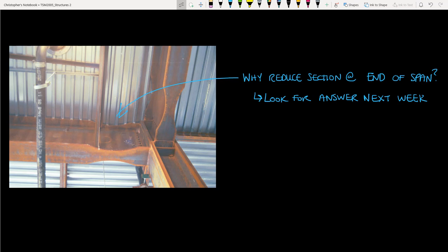This area acts like a fuse, if you've ever taken an electrical course or looked in your electrical box in your basement. Although today, we typically use breakers, which are a bit different than fuses. But basically, with fuses, when electricity enters your house, you want to make sure that there isn't too much current flowing toward your valuable electronics that could damage their internal wiring. So we place a fuse in the electrical box, which is basically a reduced section of wire. And we know that this reduced section of wire will burn out first when a power surge occurs, preventing the surge from reaching more valuable wiring.